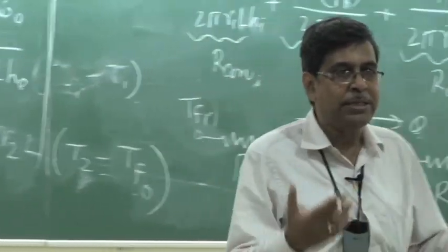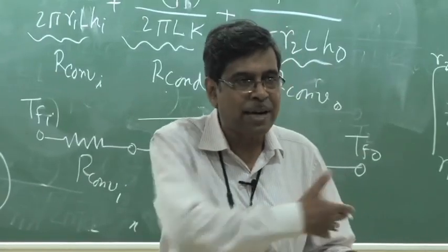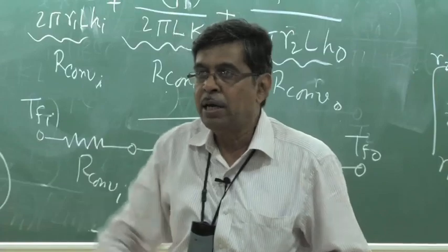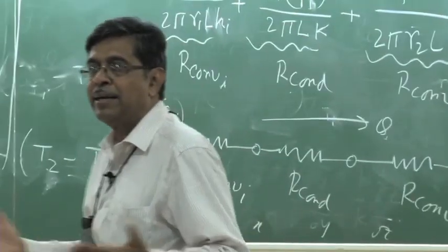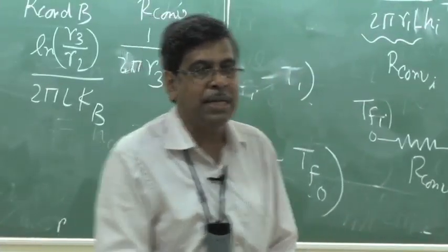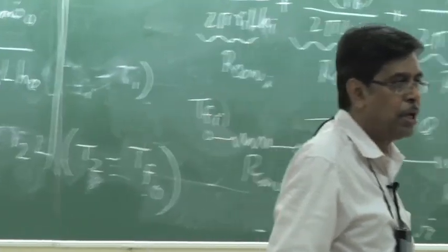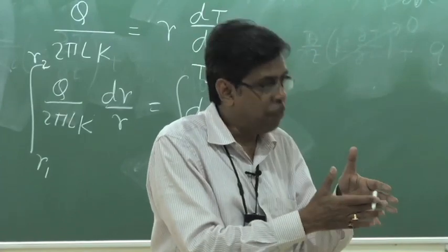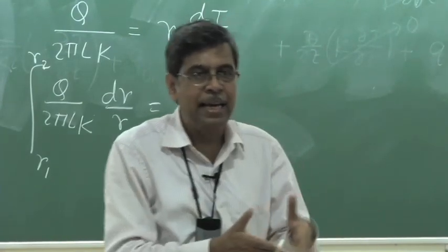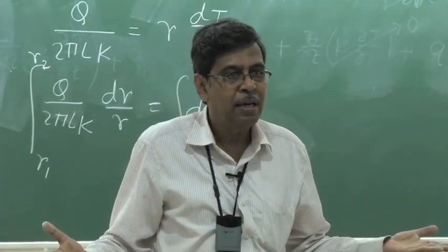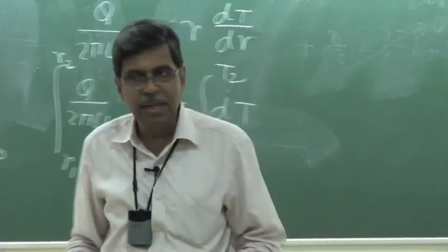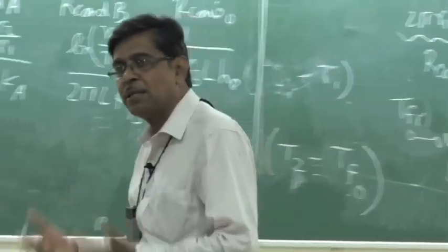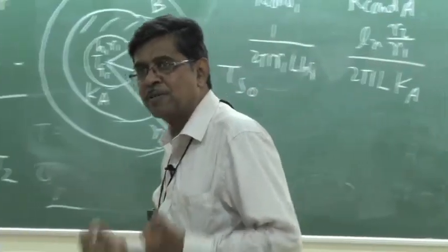The students always jump to the general energy equation. He finds that okay, he makes steady state del T 0, he makes Q 0, he makes everything 0, then you get d square T dx square equals 0, T has to be linear in x. Unfortunately, in one-dimensional heat conduction, this is an approximation of course, for a varying area, T is never linear. T is never linear. It is A into dT dx which is constant. So dT dx is inversely proportional to A. That concept has to be clear.